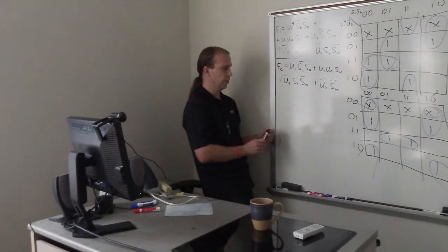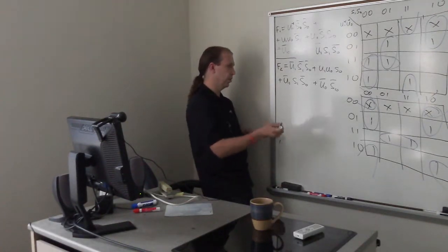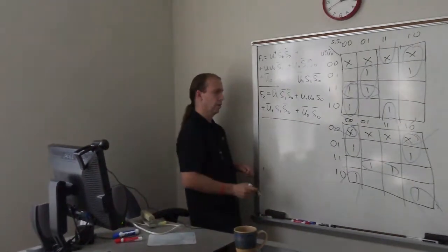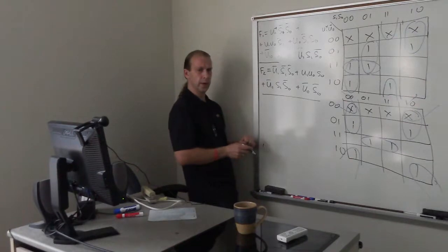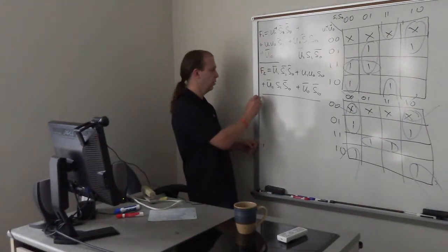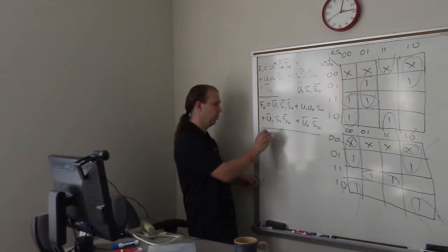So the only thing we are missing now is the output signal. And if I'm not mistaken, my output was going to be equal to high when state is equal to A or C or B or D? B or D?